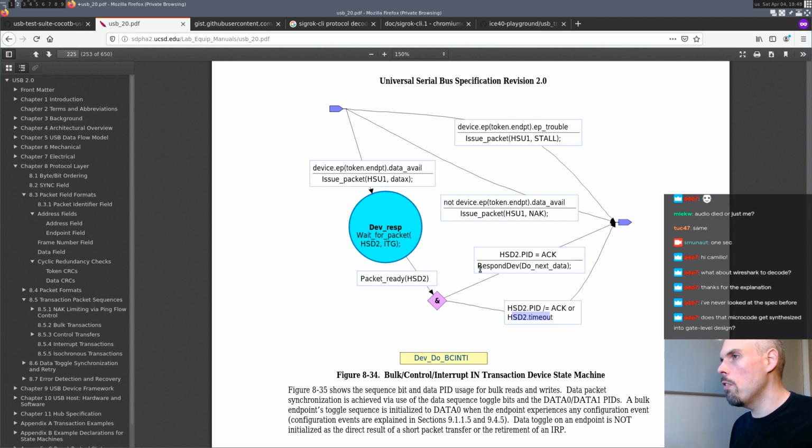You have 6.5 bit times, which, because I'm running at 4 times the frequency, is 6.5 multiplied by 4, so I've got like 24 or 25 cycles to respond to whatever condition occurs. It's not enough for a soft core like a RISC-V to execute full software and handle those states fast enough, but it's fast enough for a microcoded state machine to make those kinds of decisions.